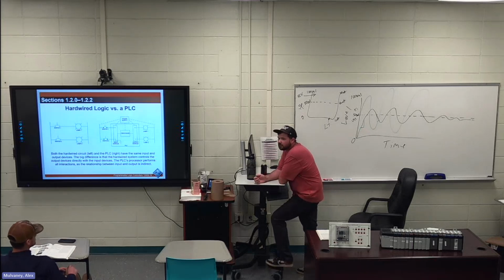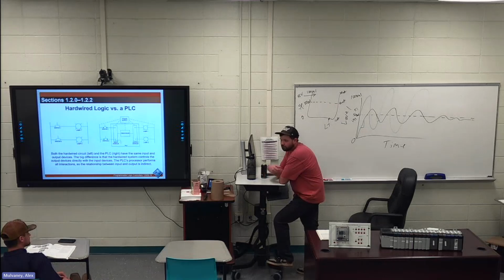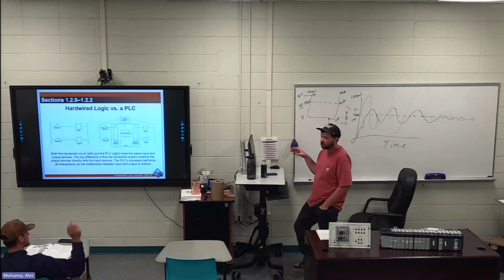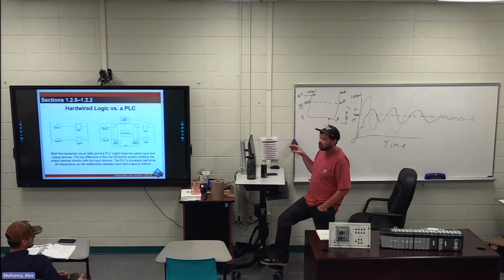The thing I would have done was check this. I would have grabbed my voltage detector and touched that solenoid and saw if it was getting voltage. Mm-hmm. And if it was, then it was getting a signal to stay open or whatever, vice versa, whatever was supposed to open. Does that get a signal or not? And then inside of it, was somebody forcing this from a PLC? They're giving it an open command. It's basically an open command, but it's sending the solenoid voltage to open.